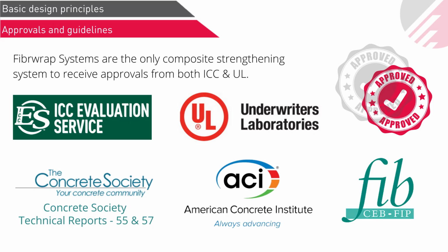If we go further into the carbon fiber strengthening or FRP strengthening using these kinds of composite materials, in terms of approvals and acceptance, the minimum approval any system you propose to be used in the UK has to have is CE marking. That's the least approval. There are some additional approvals available, for example, ICC approval, which is International Code Council, specifically for the construction industry. So some of the FRP systems have got that.